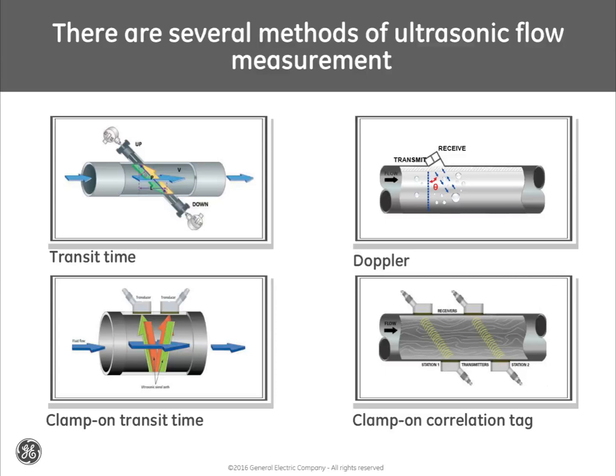The common analogy for transit time flow meters is a person canoeing on a river. It is faster and easier to paddle with the flow than against the flow. Beyond precisely measuring the transit time, accurate placement of the transducer is critical to the velocity measurement. The path length from transducer face to transducer face and the axial length are just as important as the time measurement.